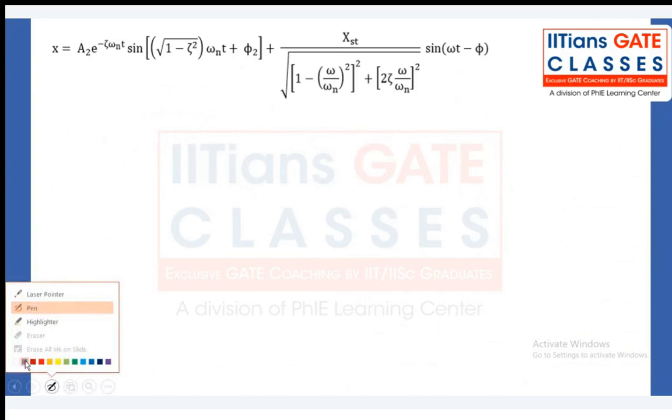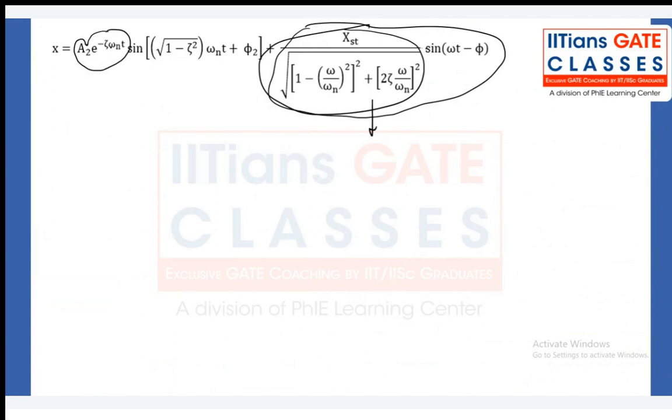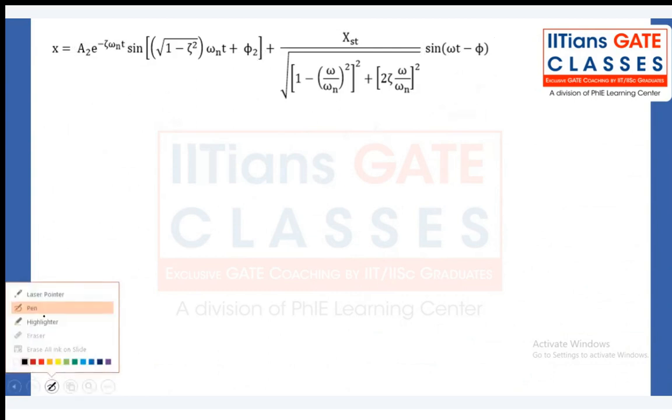And the particular integral, what is the particular integral? Anything associated with a sine will become amplitude. Unlike what we have seen, that amplitude is a function of time, which is decaying exponentially, but here it is not decaying exponentially. In fact, it is a constant. It is not depending on the time. So that's why it is called the steady state amplitude.